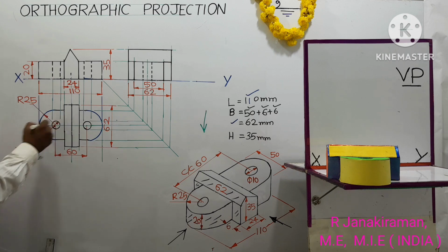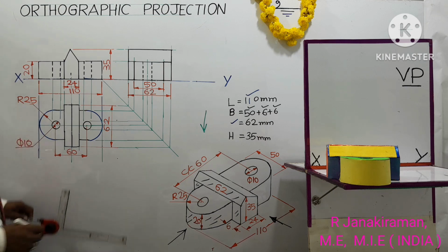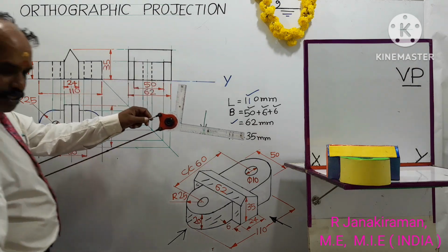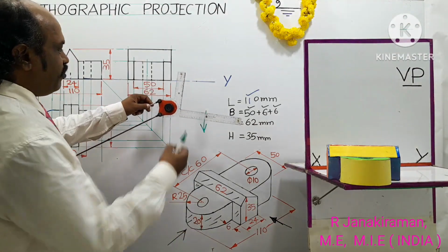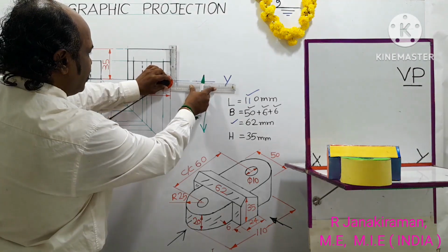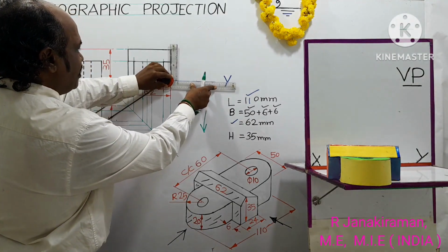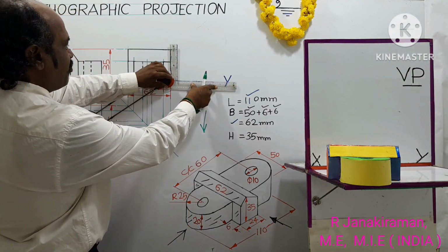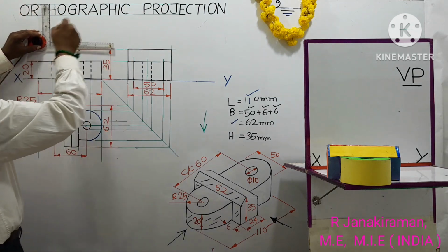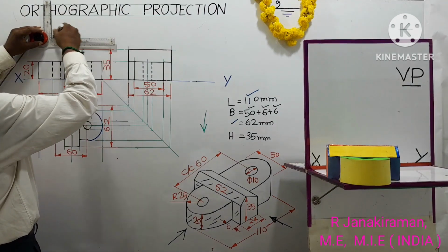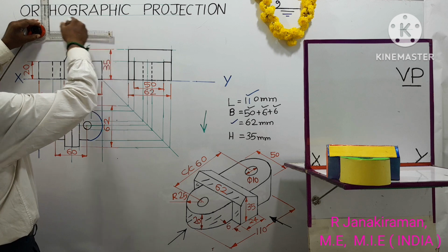The size of the hole has 2 end points. From here to here is the diameter of the circle. So I put phi, 10 is written. Okay. And you can write the name of the diagram. Reset your drafter scale. Draw guidelines for uniform height of letters. Reset your scale, release it and rotate clockwise. Okay. So this diagram is called front view. Draw 2 guidelines for uniform height of letters.